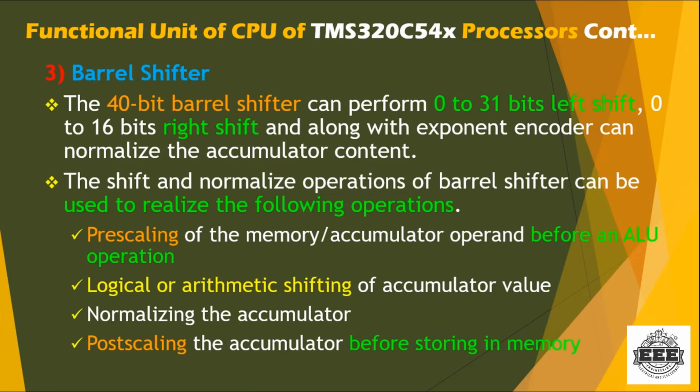This barrel shifter is used to realize the following operations. One is pre-scaling, that is, before the arithmetic logical unit operation. The second is logical and arithmetic shifting, the third is normalizing the accumulator, and the fourth is post scaling.